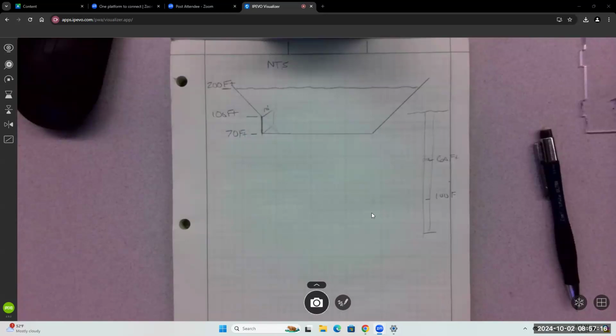So how did we do that? The force is gonna be different at the bottom of the plate than the top of the plate, right? Let's be careful: what you're saying is right, but the word you're using is wrong. Force is what? What's our unit? Pounds. Pounds is what we're looking for. So that's the first thing you want to zoom in on: they're asking for a hydrostatic force, we've got to get to pounds, right?